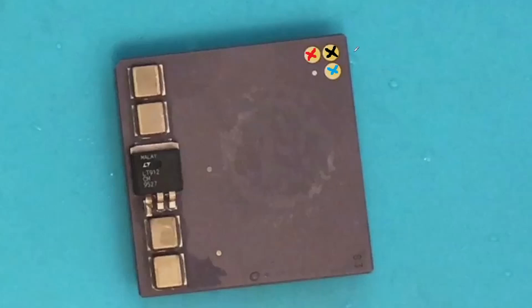So all this means that if we go actually here and short these two pins, so force the sense pin to the ground, the CPU will work with a 2.5x multiplier. Certainly you can just directly short these two, or put here a jumper so that you have the option for the two multipliers. But in my case I just put here a very small 1K resistor. Not actually needed, but I always like to use 1K resistors just to be on the super safe side.